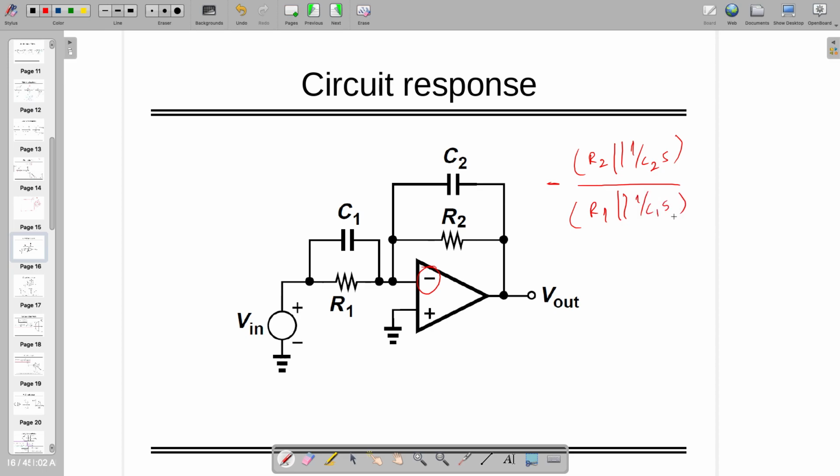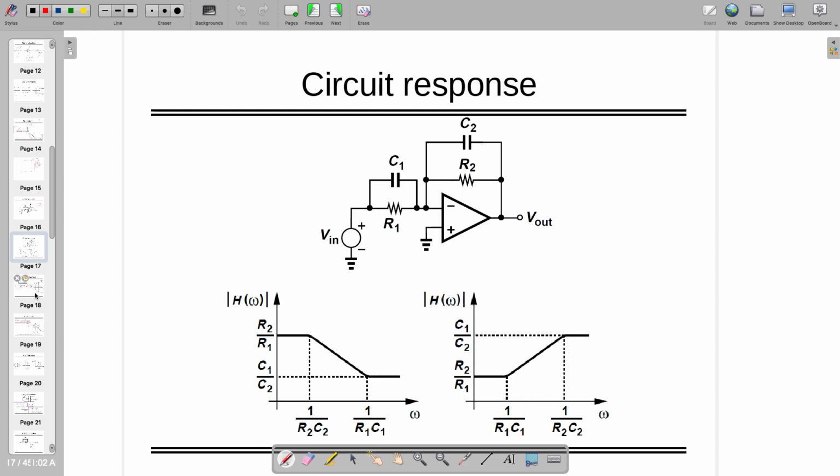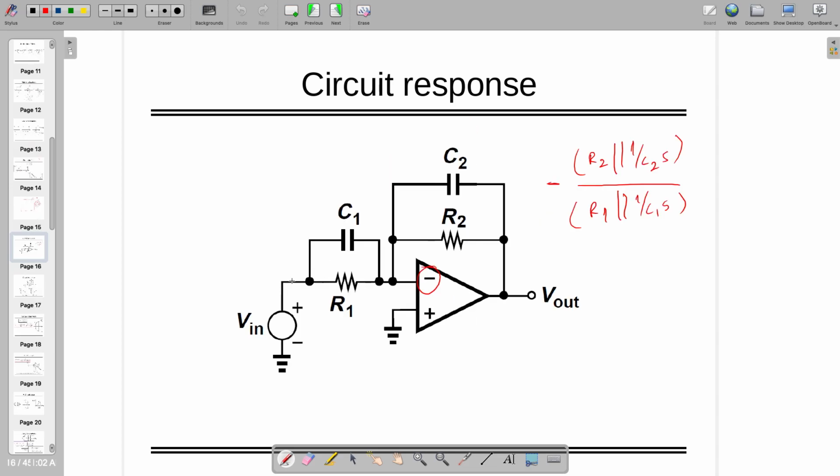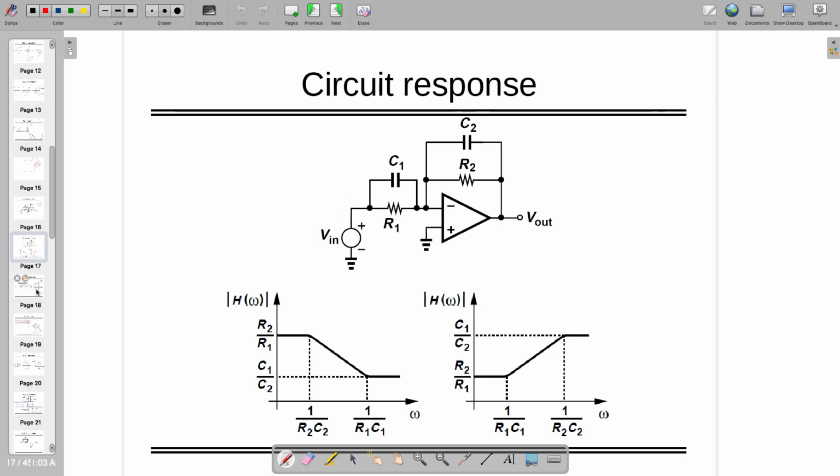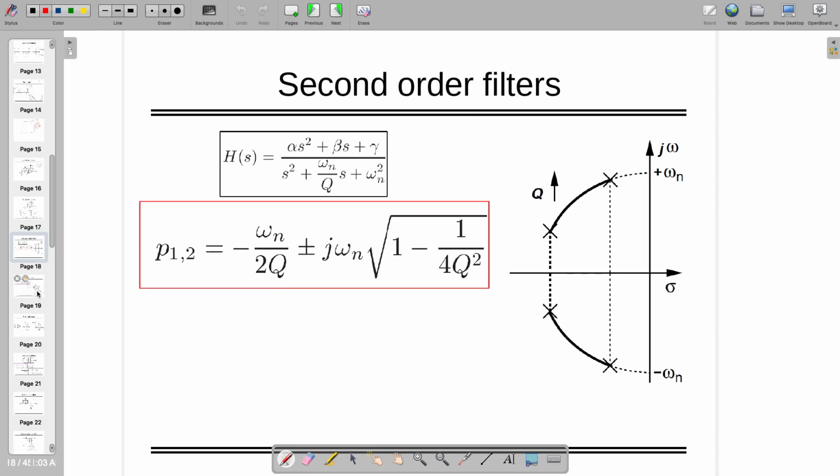Yeah, I can do this, right? Then I can find out the transfer function also. So definitely there is a path from input to output through the capacitor. So there are effectively two capacitors, but it's one capacitor. So you will have 1 zero for sure, right? So it's up to you how you make it low pass or high pass, and through that you can make the circuit as per your desired specifications.